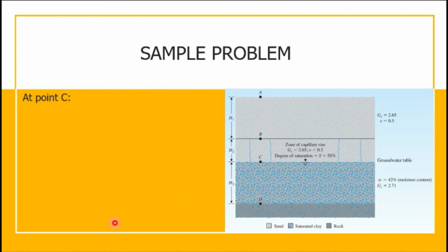And at point C, again, balik tayo sa conventional way of how to solve the vertical stresses. The total stress is equal to dry unit weight H sub 1 plus moist unit weight of this soil H sub 2 down to this point C. So by substituting the values, 17.33 multiplied by 1.83 plus 18.97 multiplied by 0.91 is 48.97 kPa.